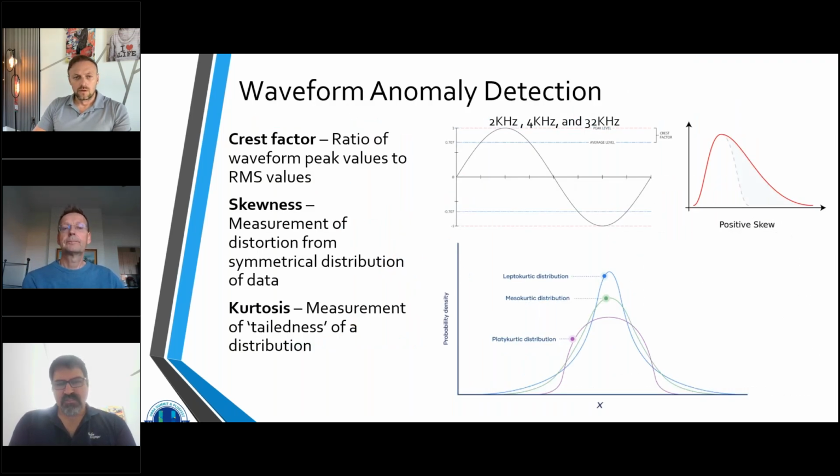So the continued innovation relative to the AMI 2.0 hardware is clearly waveform data. It's leveraged for a number of different things, between consumer disaggregation functionality as well as grid sensor standpoints. And our approach, which is patent pending, is that we apply rules to process waveform data at the meter, based on how we plot the voltage and current waveforms relative to three variables: crest factor, skewness, and kurtosis. Depending on the change in the sinusoidal wave relative to those factors, we can make a fingerprint that is indicative of different things taking place.